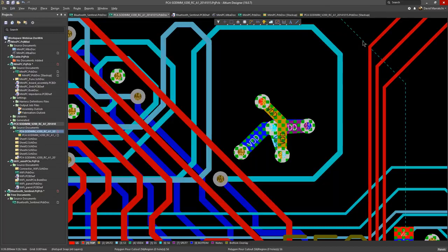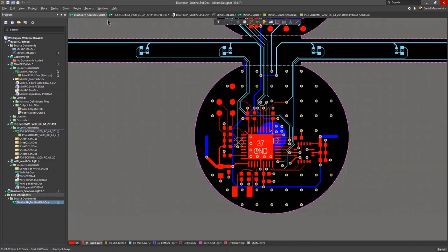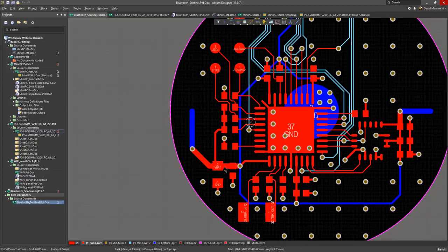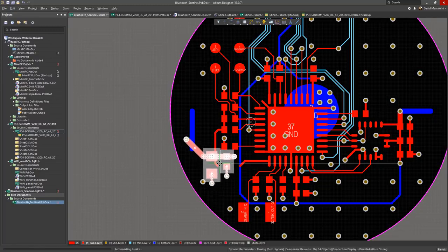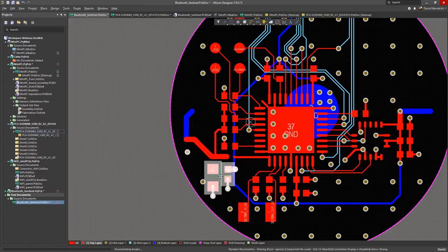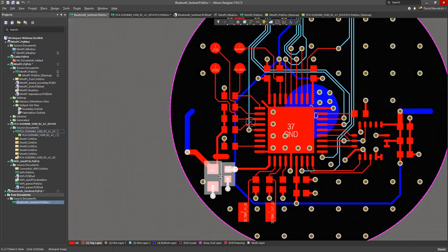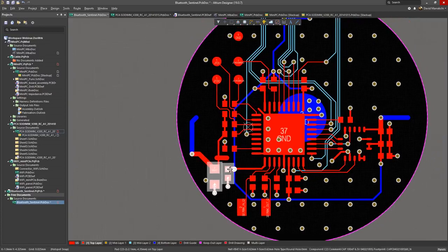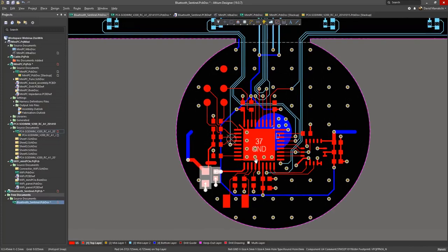Let's show some routing improvements. The first of which is component move retrace, which enables you to move any component as well as any relevant parts of routing. An example would be, as you can see here, some vias and some tracks. That enables you to move them to new locations without having to worry about any rerouting, glossing, or cleanup. Although moving a component is generally done during the placement phase prior to routing, there are times when some components need to be moved post-routing phase.